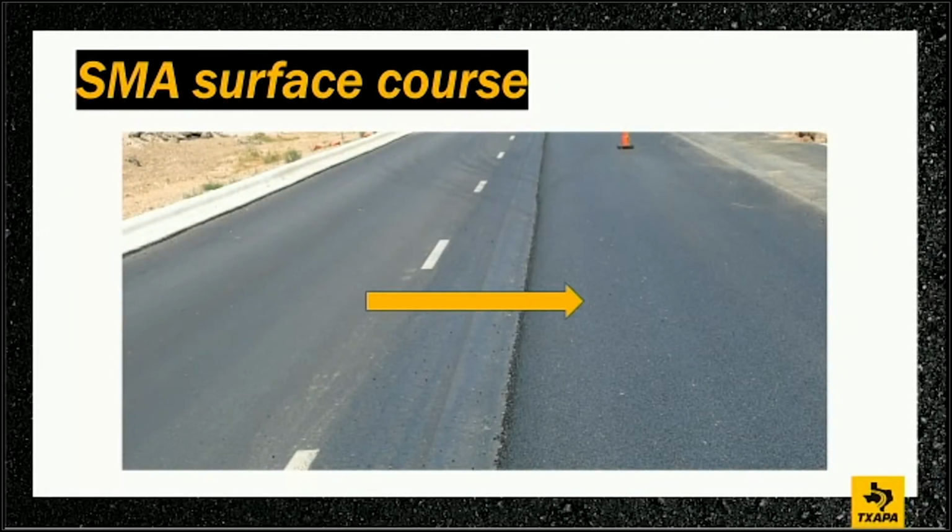Hey, a real good tip there is use the final striping layout to determine where your top joint is, and then offset your way down from there. That'll make sure you get the joints in the right place. You've got a good point there. Use the striping plan to figure out your final layout. That is a great point, Jim.